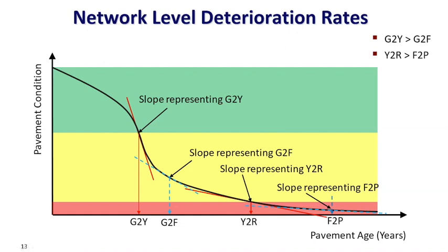The basic setup is we use the 2016 APCS data, and then through PaveM's model, we predict the 2018 performance. Using 2016, predict 2018. And remember, we also have 2018 data collected, right? Because every year we send the APCS van to collect all those data. And then we compare the two 2018 results, one predicted, one measured.